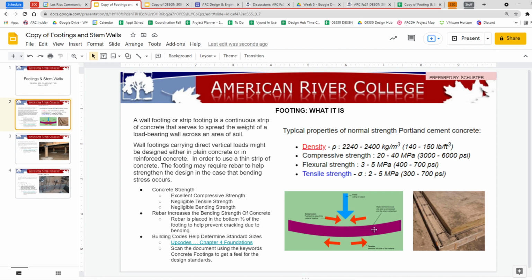This is a foundation. And if you can imagine, this is poured right here. And there's rebar in it. And it goes in a certain place and it's tied together. So this footing that transfers the load to the ground, the load is not particularly high per square feet. But look, compressive strength of most concrete is 3,000 to 6,000 psi.